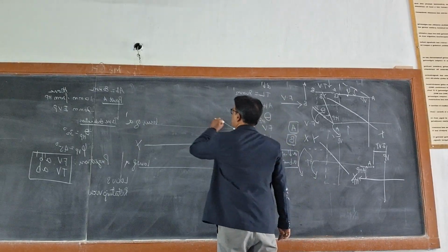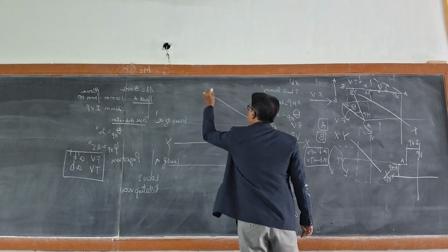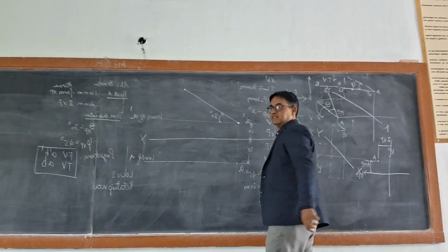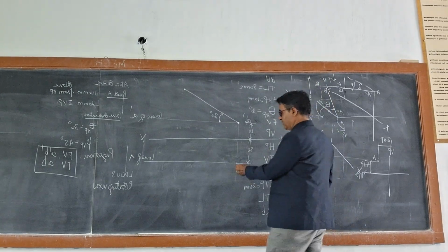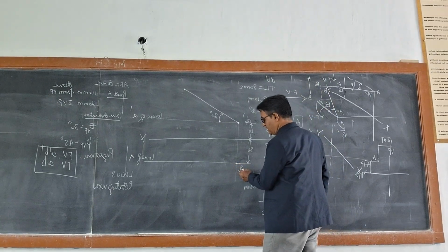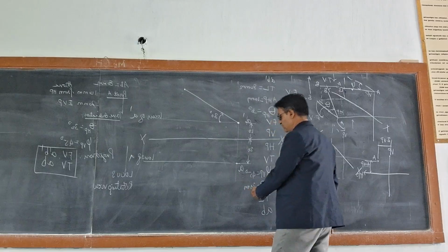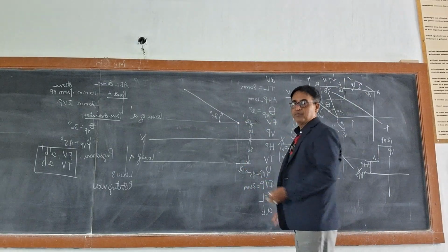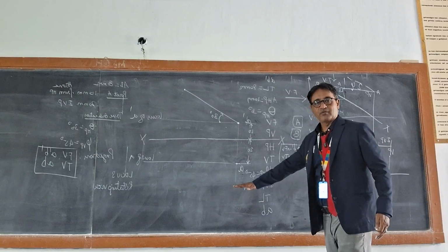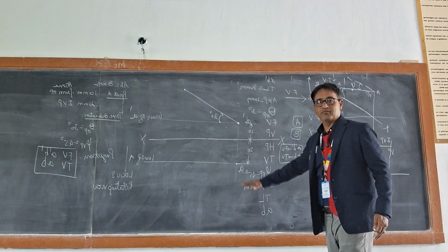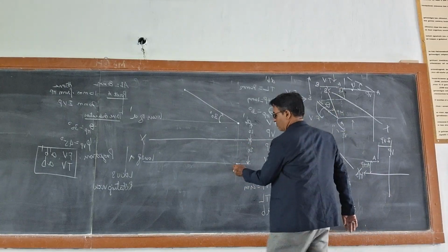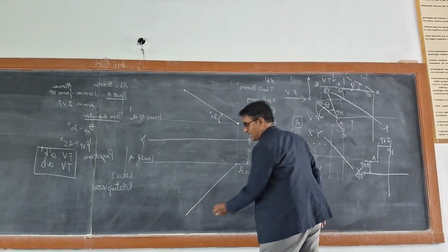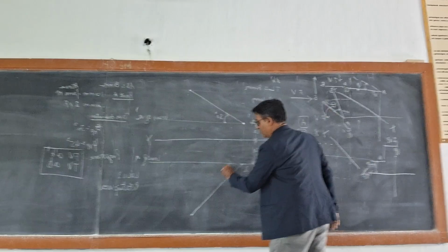So say this is 30 degrees. Similarly, below, what is the inclination to VP? It is 45 degrees. Any inclination to VP will be in the top view, where the top view is located below XY. Therefore here you make a 45 degree line, once again measuring 80 mm and making an angle of 45 degrees.